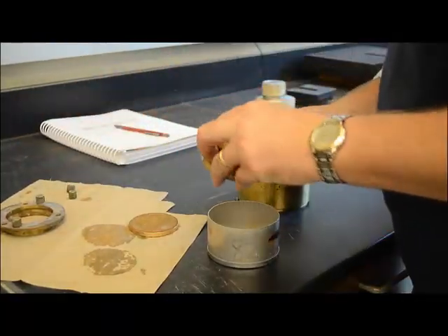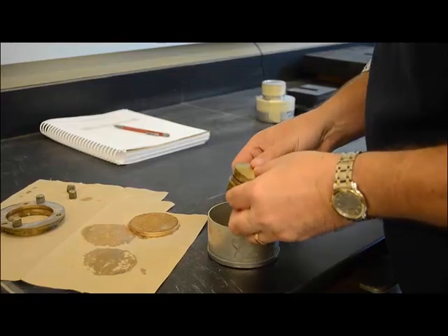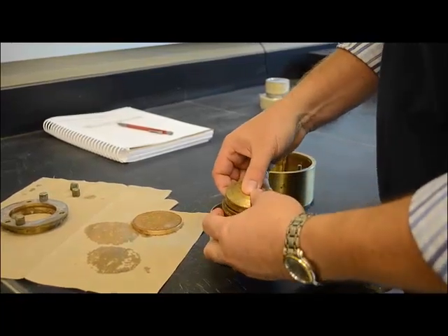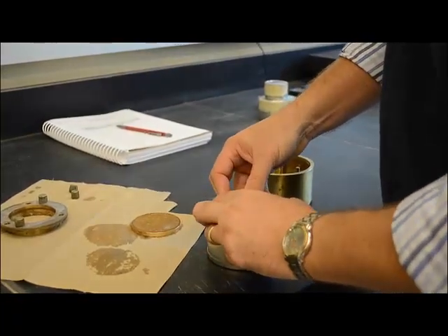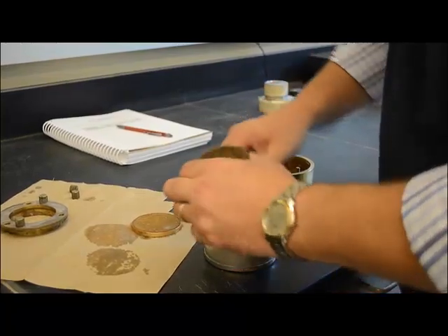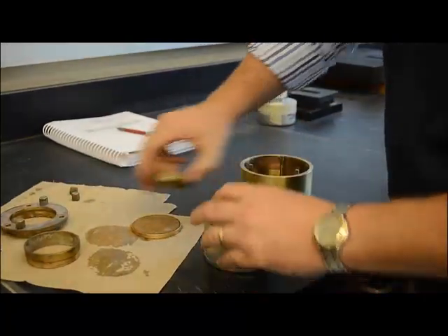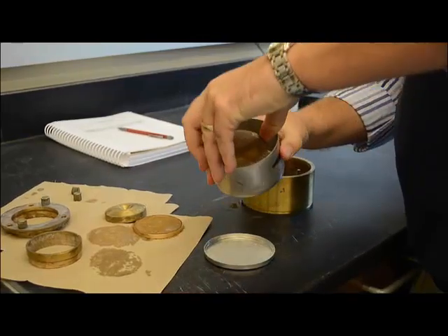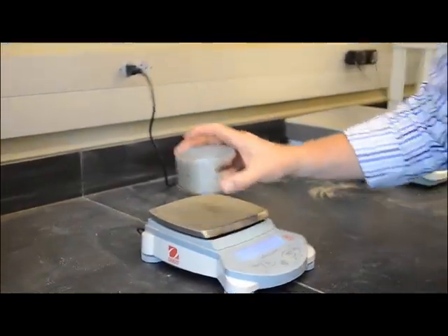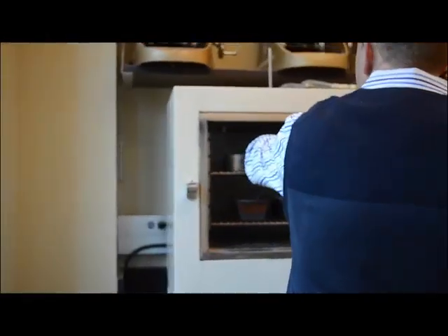Remember, we got the trimmings from the soil sample before the test began, and now we want to get the moisture content of the soil sample after the test is over. So place that into a dish with just the sample itself, no porous stones or anything else. Weigh it, get a wet weight, put it into the oven, and get a dry weight 24 hours later. And that's the complete test.